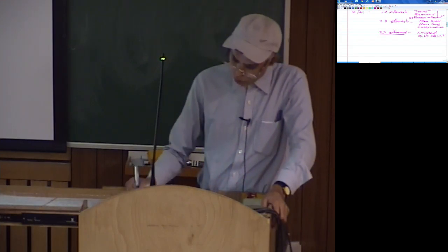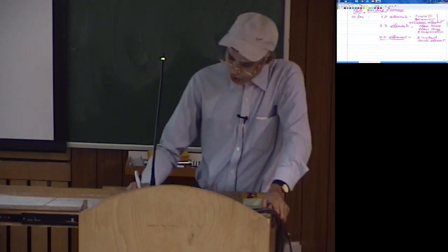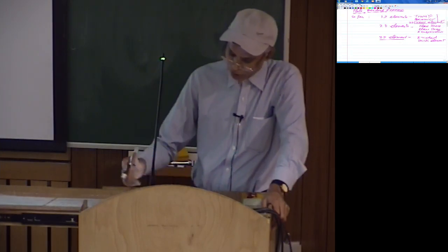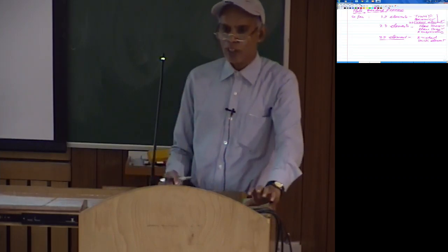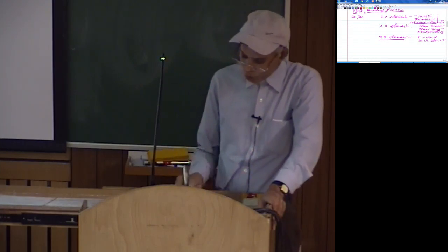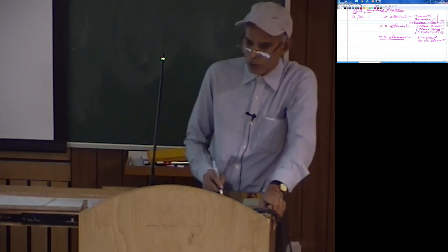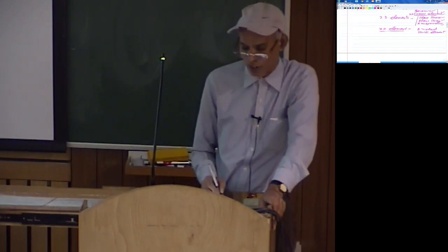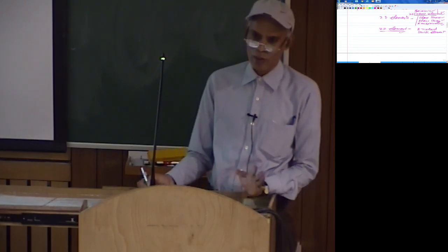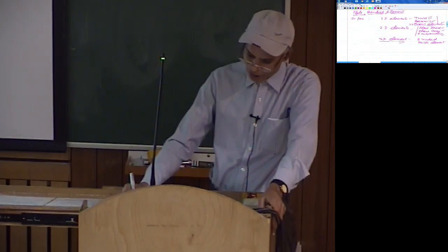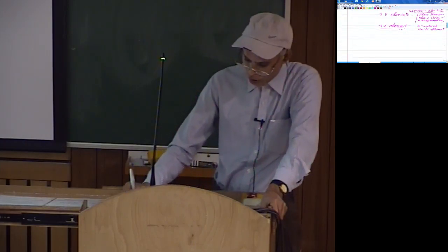Now if you look at it in terms of loading, here we considered in-plane loading, transverse loading, and of course you can have in-plane, axial as well as bending loads. In all these problems we only considered in-plane loading. Now if we want to do 2-dimensional problems where 2 dimensions are significant compared to the third one, but the loads are transverse, you can still use a 3D element and model the problem, but there is another group of elements known as plate bending elements. This is the topic which I am going to start today.